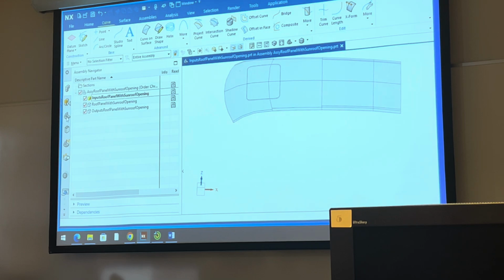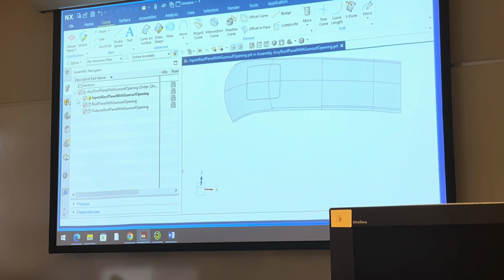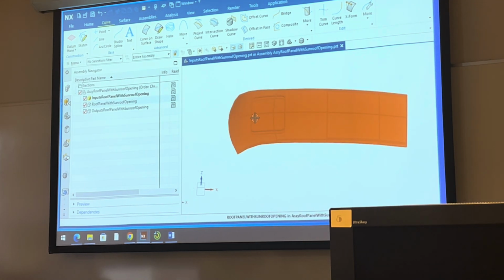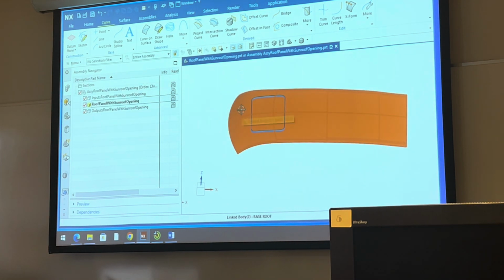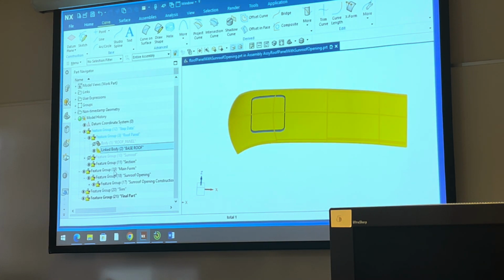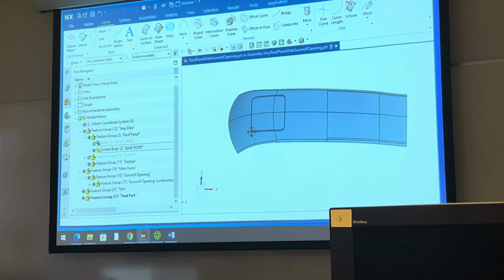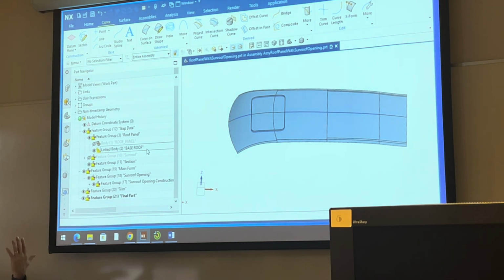We put it in the inputs here in our assembly, like so. And just to make it so we're following our methodology like we were doing before, the inputs came from somewhere else, and then we're using the inputs in our working file. So we took that surface from the inputs, and we made a wave link from the inputs file to our working file. Most of the surfaces we just copied and pasted, they were kind of dumb surfaces. This one we put in the inputs, and then from there we brought it in as a link. It is a link to a non-parametric surface, but it's now linked to another file. So anyway, that's what we did last time.